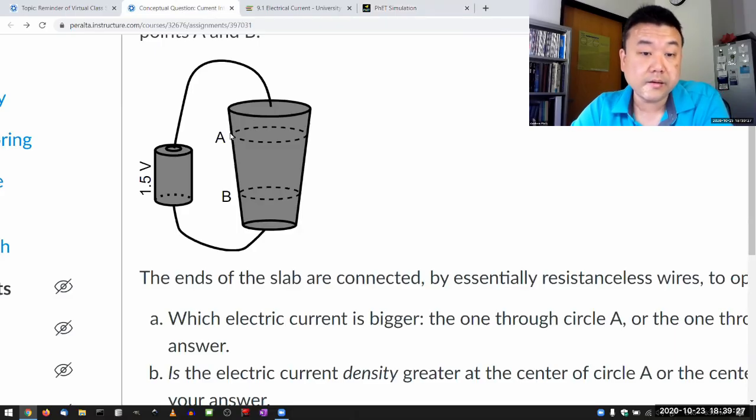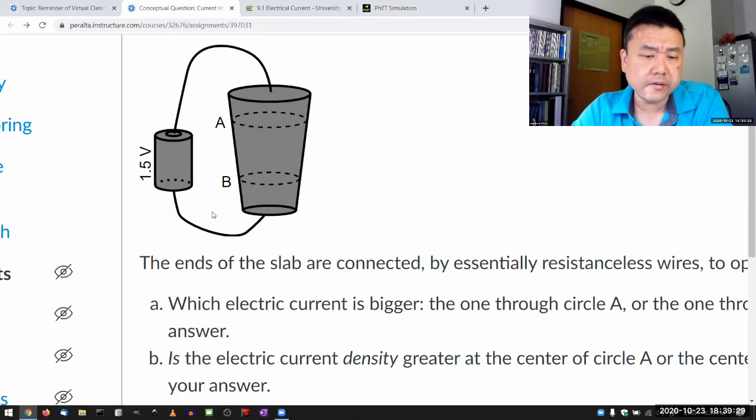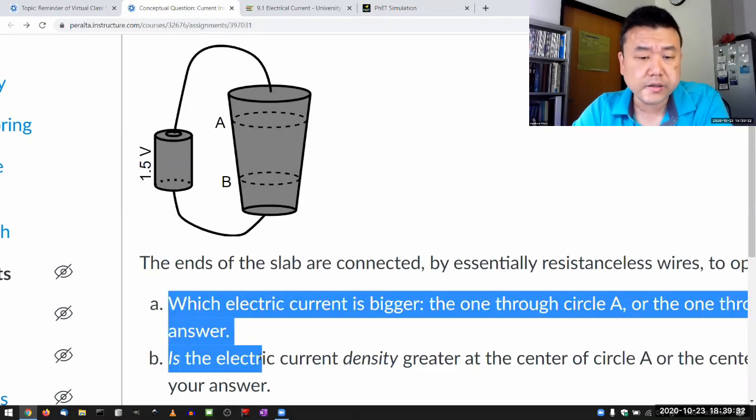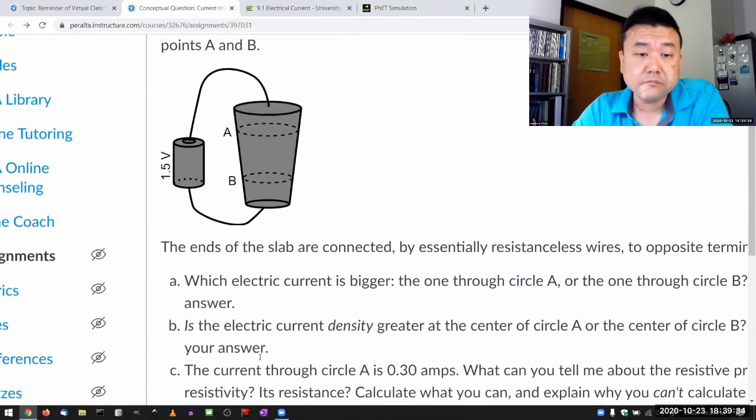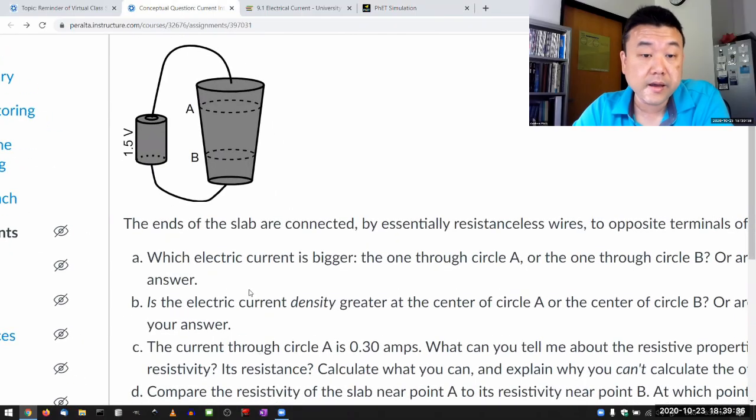And you can see a similar situation with the electrical current flow here and voltage here. So I said, referring to why the correct answer here might be unintuitive, that resistance per length would be less here compared to here, but still the amount of electric current flow is the same. Well, if you look at the voltage change per length, you will find that the voltage change here is less per length compared to the voltage change here per length.